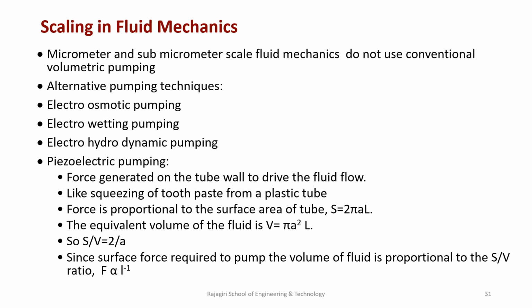So the S by V ratio can be calculated as 2 by A. Since the surface force required to pump the volume of fluid is proportional to the S by V ratio, the force will be proportional to 2 by A. That means A is proportional to the linear dimension L. So force will be proportional to L raised to minus 1.